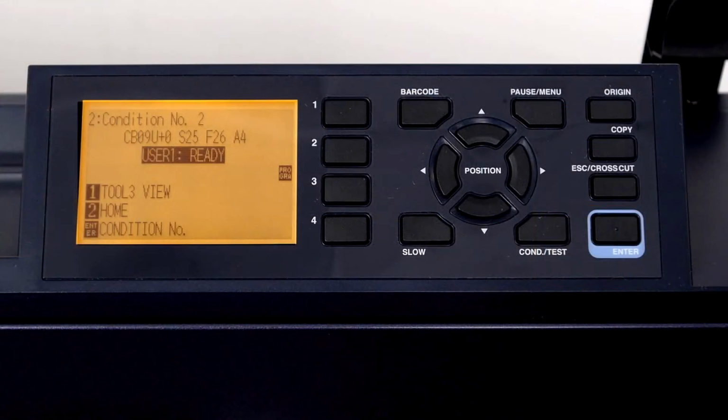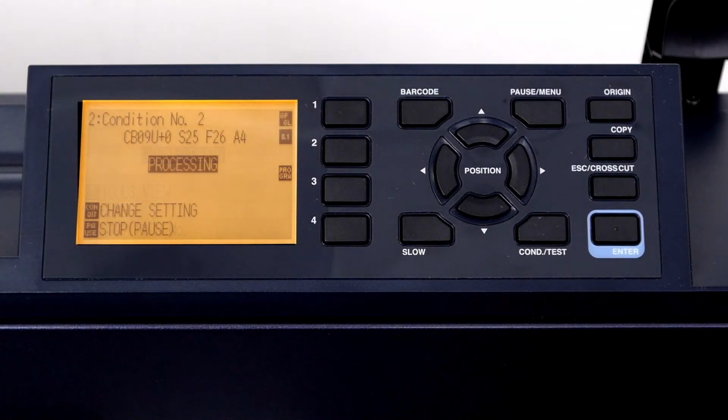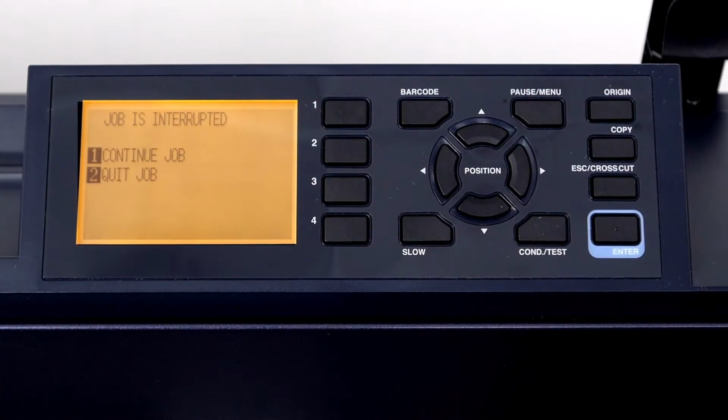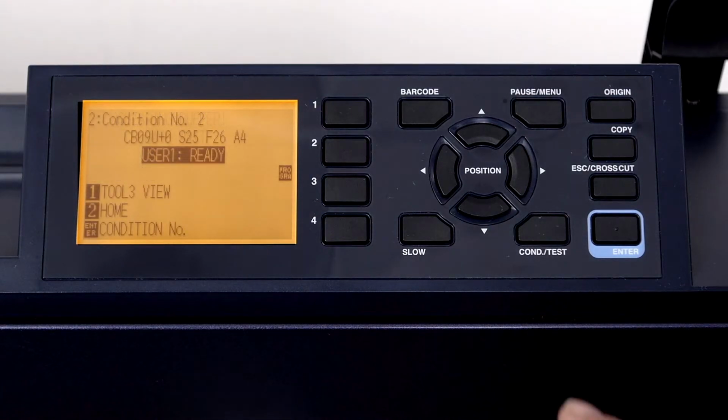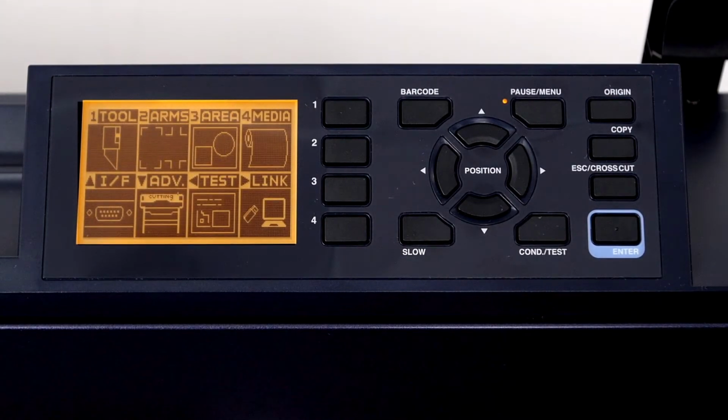Let's go over the menu structure and how to navigate through the menus. To access the menus, we need to press the pause menu button. If the FC9000 is online and operating, this pauses the operation of the plotter, and it will display on the LCD screen a choice of continuing the cut or to quit. When the cutter is in ready mode or stationary, pressing the pause menu key will display 8 groups of menu